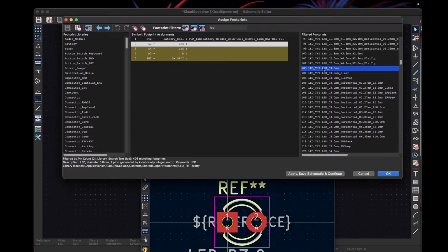For this example, I'm going to show surface mount ones because surface mount stuff seems a little bit scary and harder to work with, but the parts are much cheaper, and once you know how to solder them on, it can be really quite easy to work with. You just need a pair of tweezers to hold the part while you're doing it, and I can show my graphics from a soldering workshop that I teach that shows it in just one slide. It's really nice if you're going to use it for any small wearable design, because then it's not big and chunky and getting in the way.